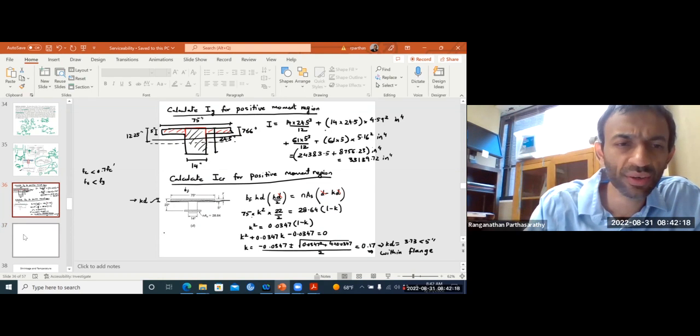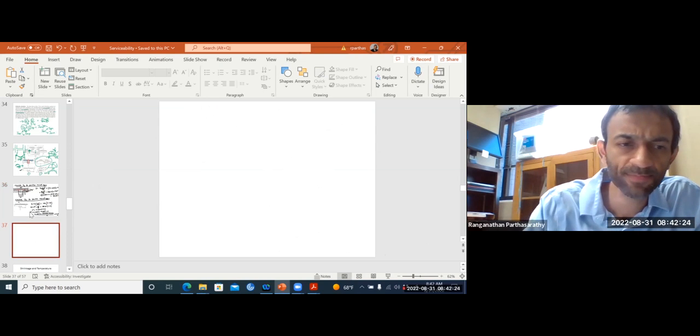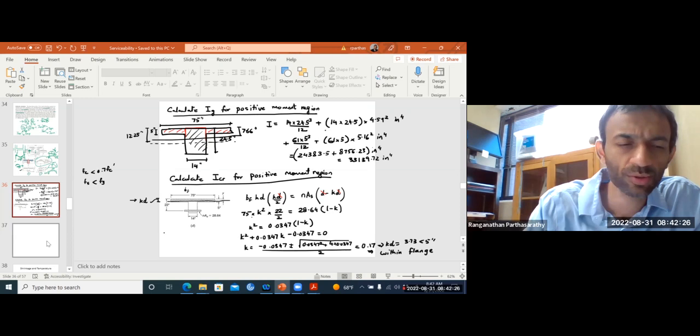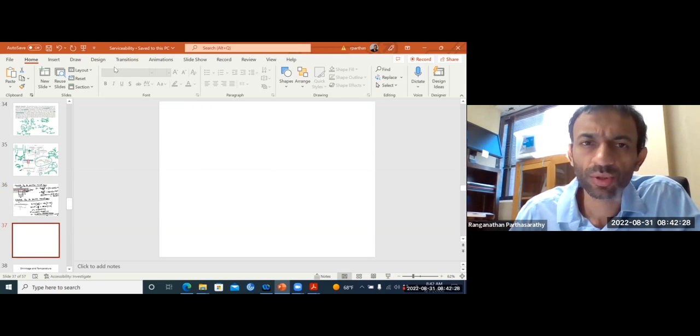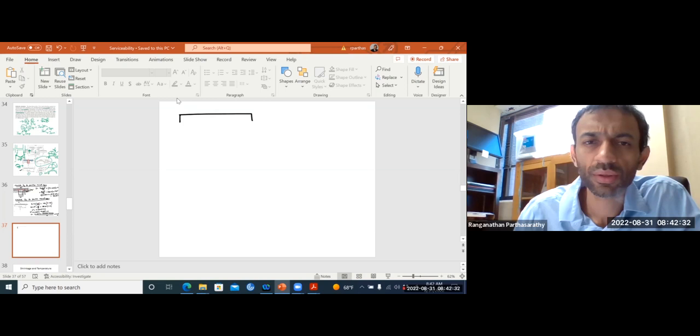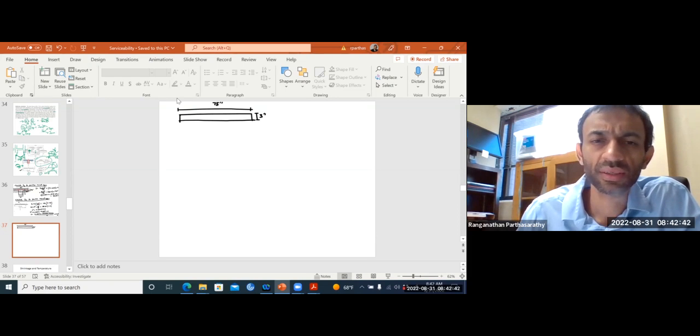Now that we got our neutral axis, what is our moment of inertia? So that's 75 inches times 3.73 cubed over 3.